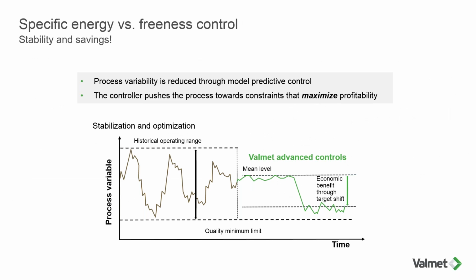Another step that can go on and improve refiner performance even further. Specific energy controls has its flaws as well. It pretty much does not take into account what kind of kappa variability, what kind of quick flow and consistency changes. The refiner is just not fast enough to react to all of that. And all it does is it grabs whatever is coming in and it changes it to something coming out, probably accenting whatever issues it had.